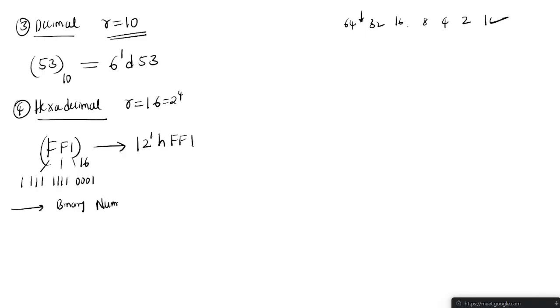Suppose you take the binary number tick b 0110. What is the size? Tell me. Size is not declared. Either it can be 3 or 4. If it is 110 or 0110, it is the same. But size is not declared, so how will you decide?